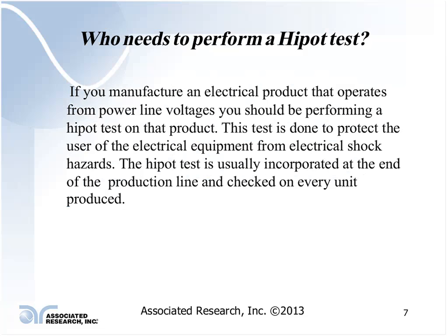Who needs to actually perform a Hipot test? Well, if you're manufacturing an electrical product and it's operating from line power, you really should be performing this Hipot test, or routine production line Hipot test, on each and every product that you produce. This test is really done to protect the user of the equipment from any potential electrical shock hazards that might occur due to faulty insulation within the product itself.